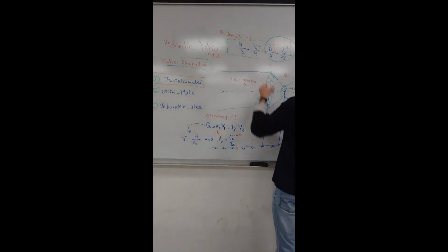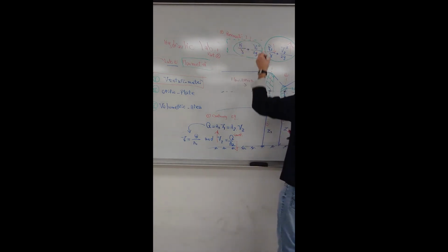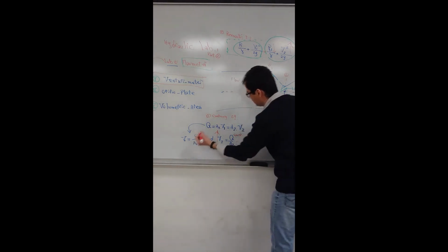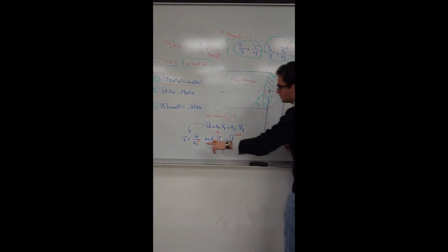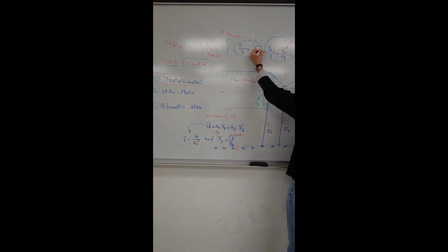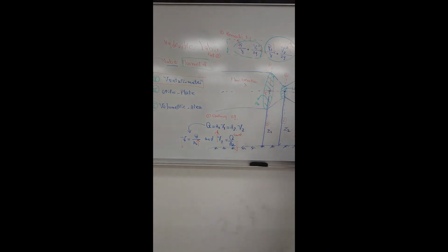Similarly, in cross-sectional area 1, area is higher. If it moves from 2 to 1, area increases, so velocity drops. To compensate the second part, pressure should increase.